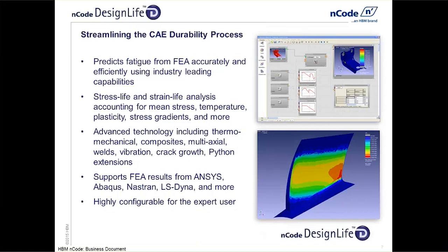We can look at vibration, which is just doing fatigue in the frequency domain. So instead of supplying a time history, you'd be supplying a PSD. It's essentially a virtual shaker table that we can simulate. We support all the major FEA codes: ANSYS, Abaqus, Nastran, LS-DYNA, and there's a few others as well.